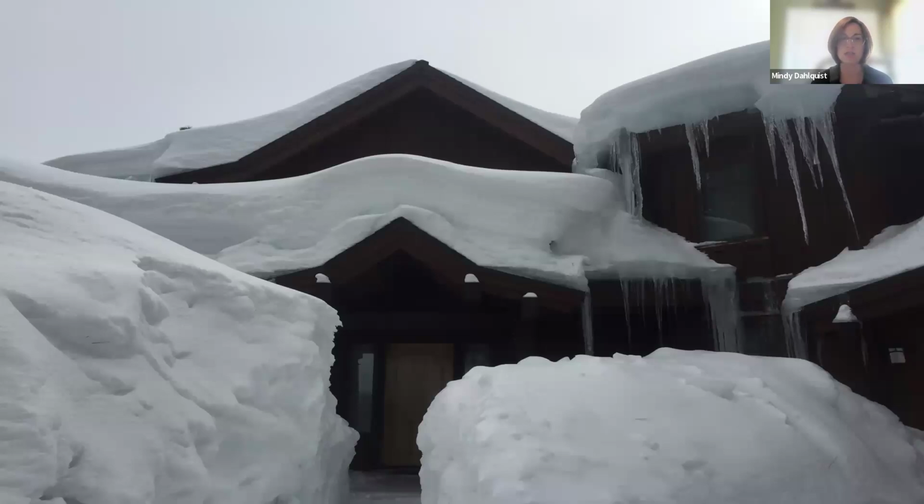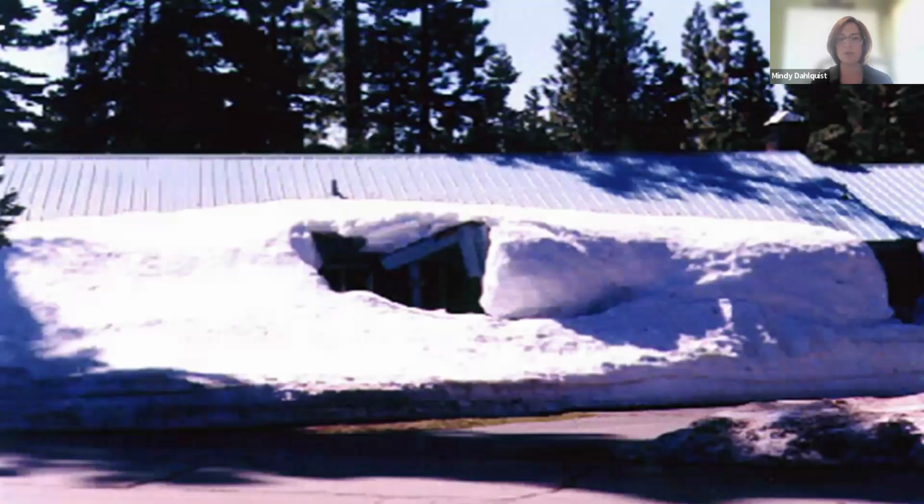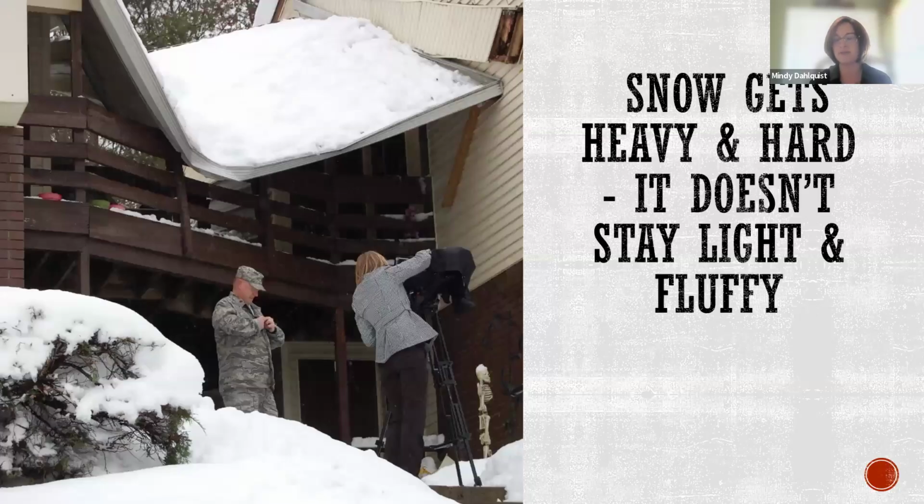So some of these houses are going to maintain very large loads of snow on them. And then it's just a given time. There's really no exact time that that snow is going to let loose off of that roof. So making sure that you're always designing to the worst case scenario when you're looking at heavy snow accumulation areas is very important. But we're not looking at just a light little skiff of snow. When the snow gets heavy and does accumulate on the roof, it glaciates. So it doesn't even have to be heavy at that point, but it will actually freeze into one giant large mass on the roof. That snow gets heavy and hard. It does not stay light and fluffy.